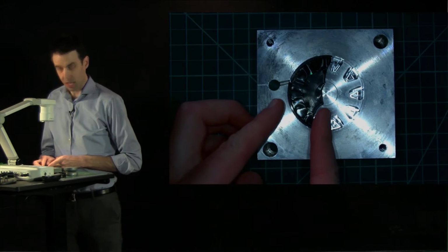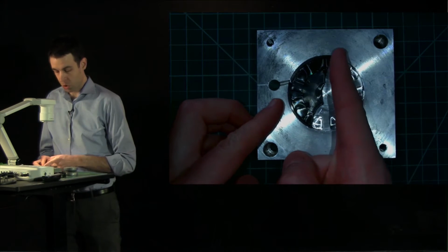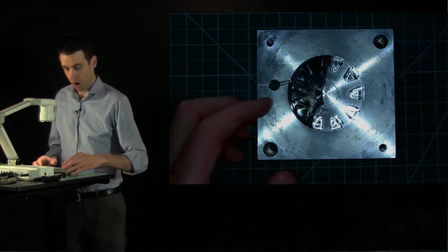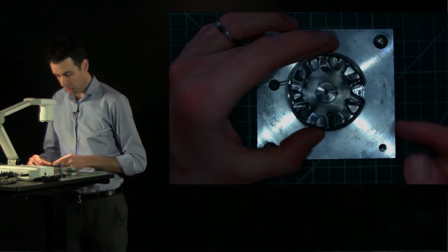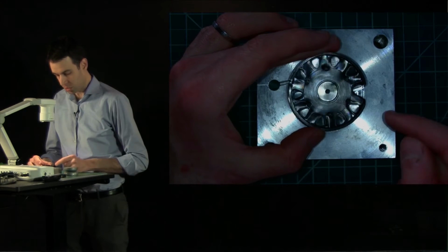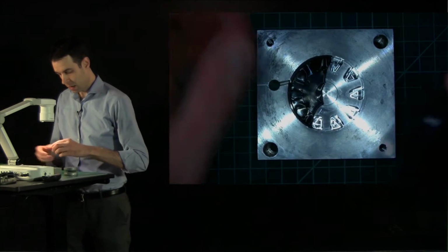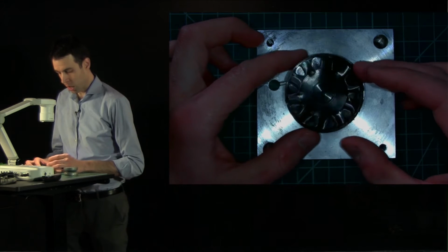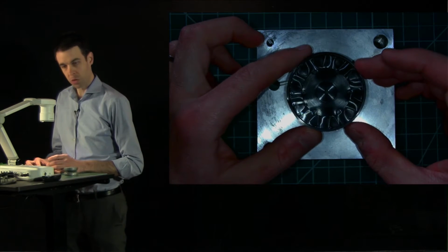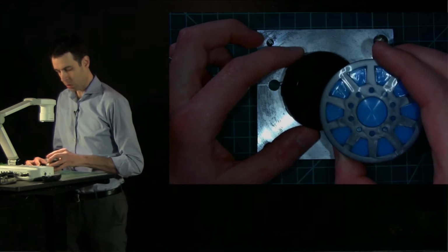And here their shot size, the amount of plastic they injected, was only enough to fill the mold this far. And over here I have their almost completely filled part with a little bit of a short shot on the far side here, and then the completely filled component that was then transferred to the blue color and for which the parameters were adjusted to make the final components of the yo-yo.